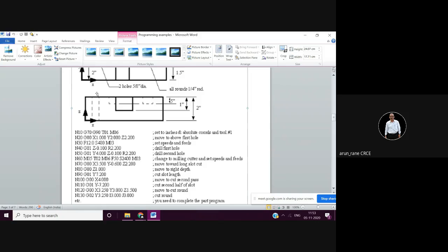So it is good practice that you bring the tool here, start the spindle, and in the next block start the coolant. So the coolant is not spurting away. If you start it from here, the coolant will fall on the whole outside environment, the surroundings, and it will become oily and an accident will happen. And of course the operator, or whoever is there, will also become wet.